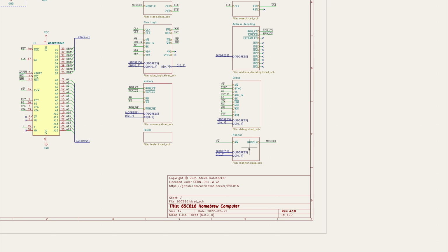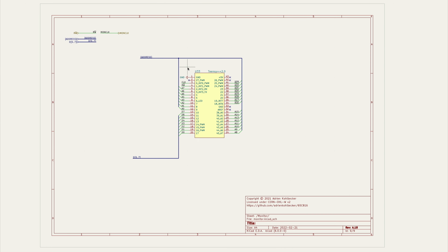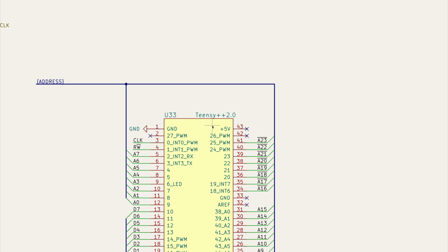And finally, I think it would be good to have these available in the monitor so that we can ignore cycles that are not valid addresses and also synchronize the opcode fetch. This will be useful to build a disassembler in the monitor. So let me add these. Thankfully we have 2 pins still available easily on the Teensy.